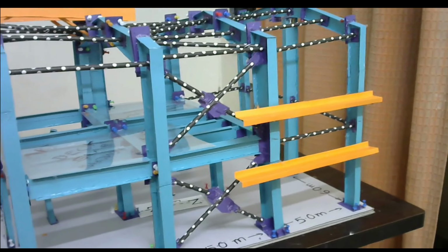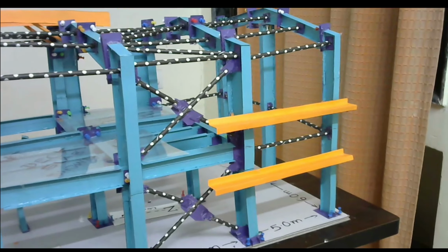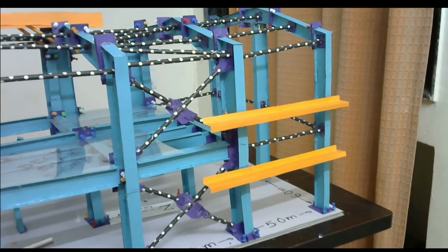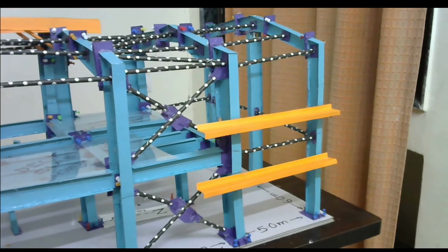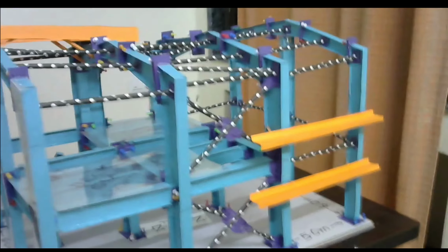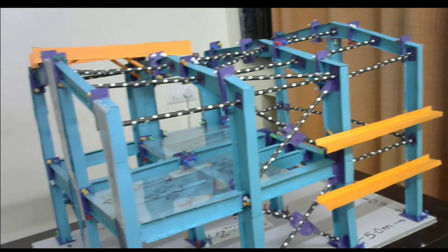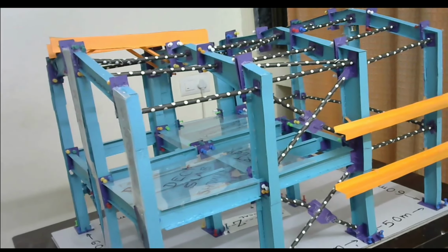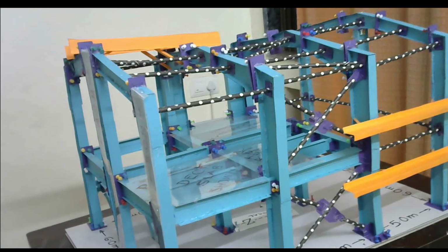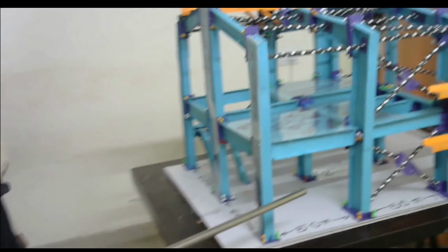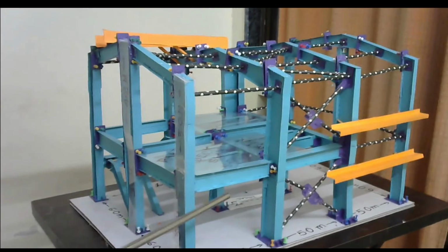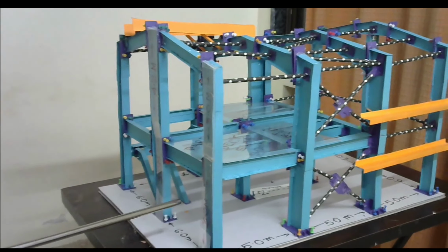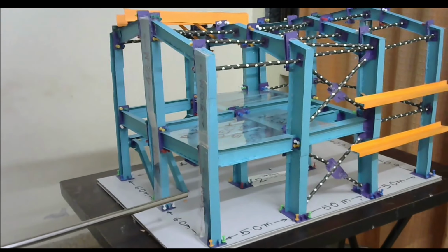With this, we have covered the effective length factors of all the members. I hope you will be able to apply the concepts you have learned in practical design. Now let us move to STAAD Pro again, and we'll define other parameters in STAAD Pro itself, like yield strength, then ultimate strength, then slenderness limit, etc., that we can discuss in STAAD Pro.